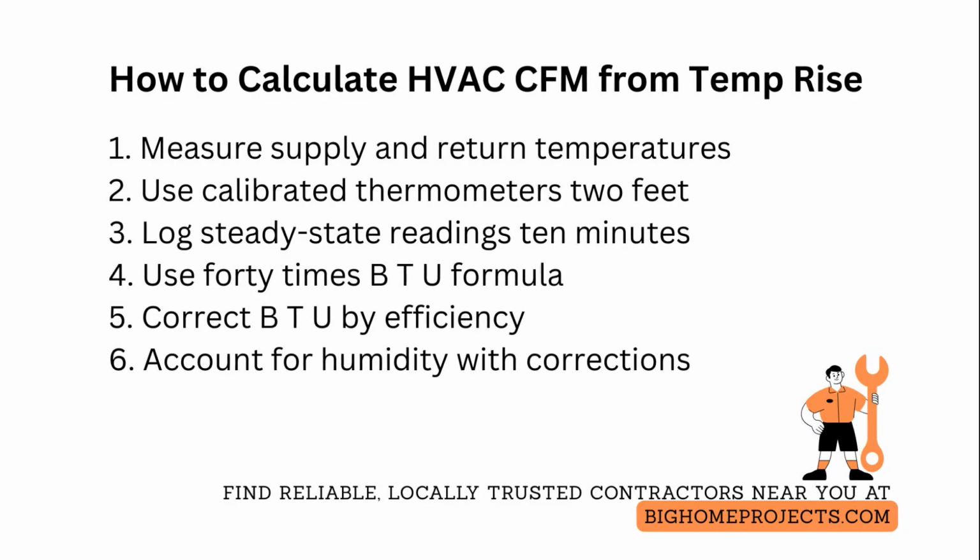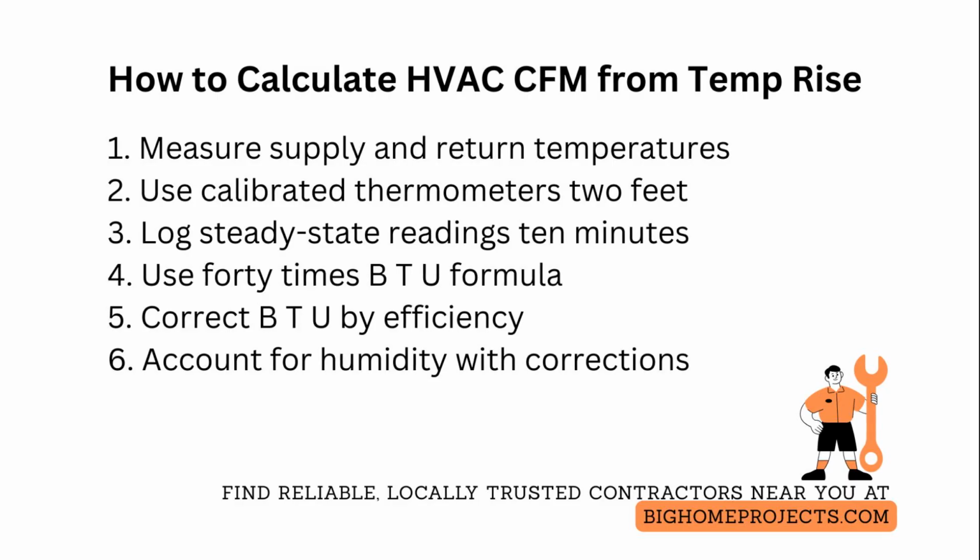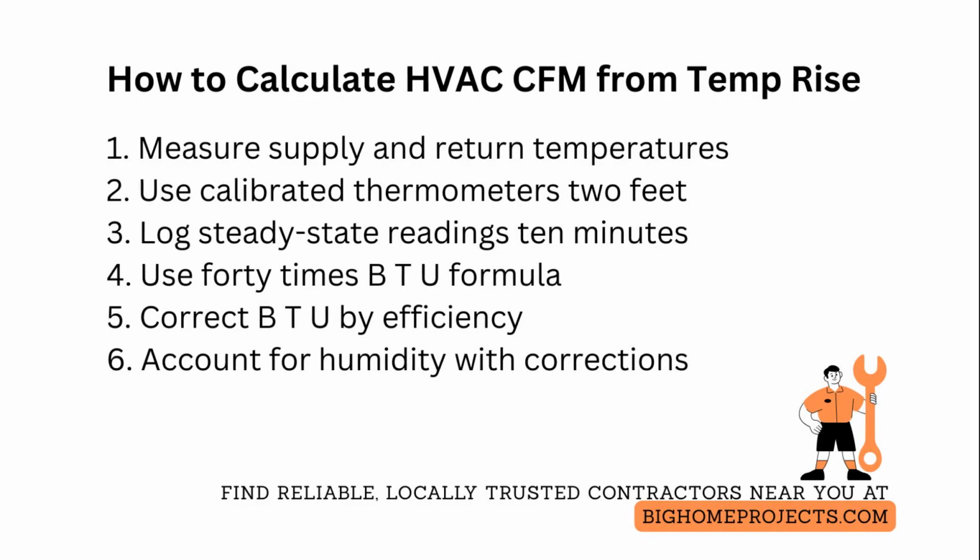Before and after any test, inspect filter pressure drop and document filter type and age, since a clogged filter can mask low CFM and create false normal rise values. Change the filter and repeat tests to verify.